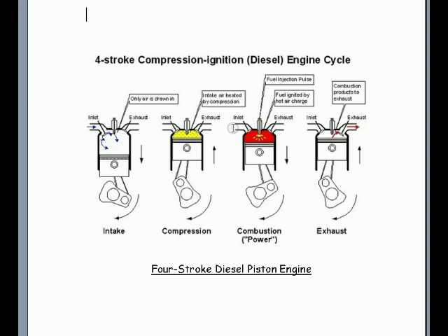Kerosene is used on gas turbine jet engines because gas turbine jet engines operate by heat of air compression just like diesel piston engines do. So a hard to burn, slow burning fuel like kerosene, jet fuel, or diesel are used in diesel and gas turbine engines. Once the engine lights off and fires into operation, the heat of air compression is sufficient to raise the temperature to ignite the fuel.